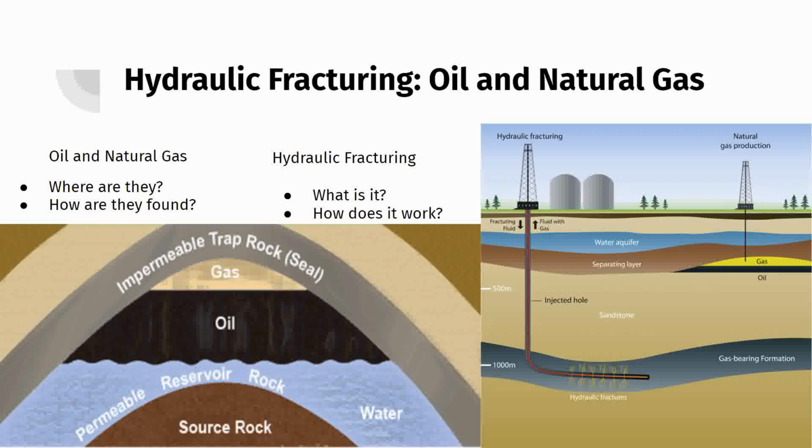Hydraulic fracturing uses sand, water, and chemicals to extract oil and natural gas from rock reservoirs. A drill digs down vertically, then once next to a rock reservoir, drills horizontally into the source. Next, a mixture of sand, chemicals, and water is used to fracture the rock. This process creates many cracks in the rock, and as the water is removed, sand is left behind, which allows the cracks to stay in position, preventing the rock from caving. This allows for gas and oil to be extracted from the cracks in the rock.